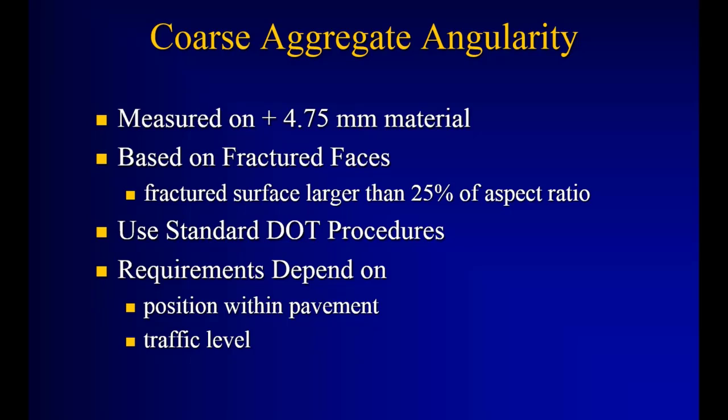So what we look at is, does it have a clean and clear and well-defined edge? And does it cover enough of the aggregate, the aspect ratio? If it's just nipping an end off a piece of an aggregate stone, say 3/8 inch aggregate stone, that's not a fractured face. It's got to cover a larger cross-sectional area to get the impact of this fracture edge and texture that we get from fractured face.